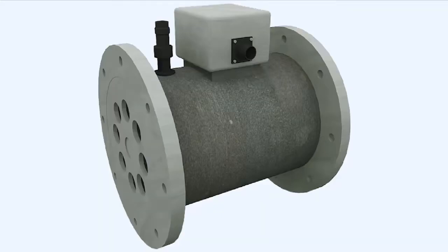An electronic torque meter system, such as the one shown here, utilizes the angular displacement of a driveshaft, which is placed between the engine and the propeller drive. This displacement, being proportional to the transmitted power, is measured electronically, and the signal thus generated is used to drive the needle in the torque meter. This system is inherently lighter and more reliable than the hydraulic system.